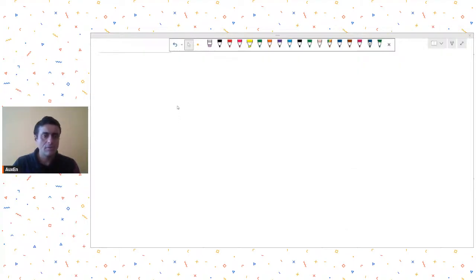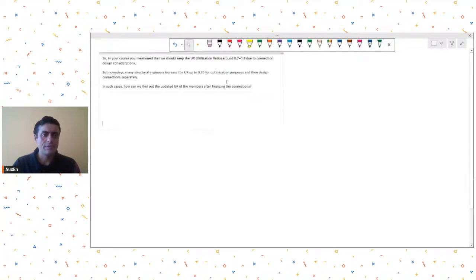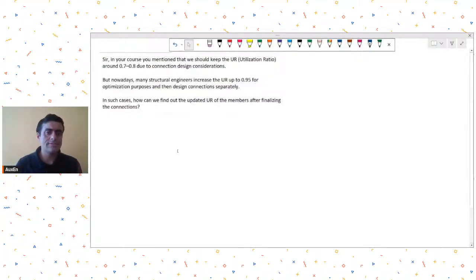And the first question is from Mr. Rohit Raghav. He is a postgraduate student joining from Faridabad. I hope the question is visible on the screen. In your course, you have mentioned that we should keep the utilization ratio around 0.7 to 0.8 for connection design considerations. But nowadays, many structural engineers increase the ratio up to 0.95. In such cases, how can we find out the updated UR?